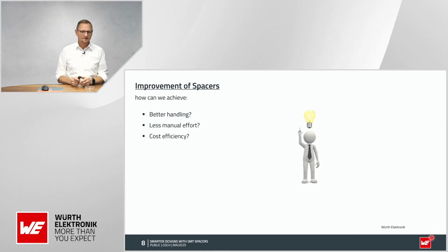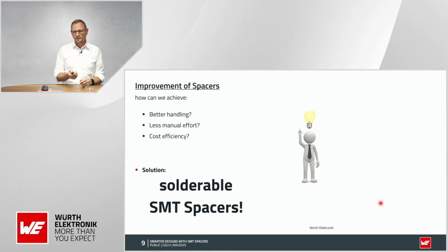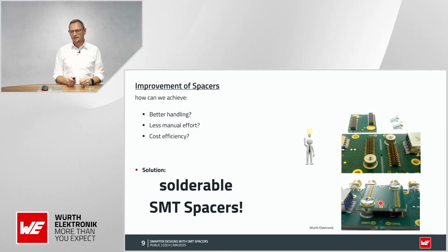And you might have guessed the solution. We're talking about the solderable SMT spacers. That means you can place this kind of component somewhere on your PCB and solder it together with other components. So it might look like this example here. You can see the components here, here are the spacers, and there's the bridge that goes on top, and here you have the fixation now.